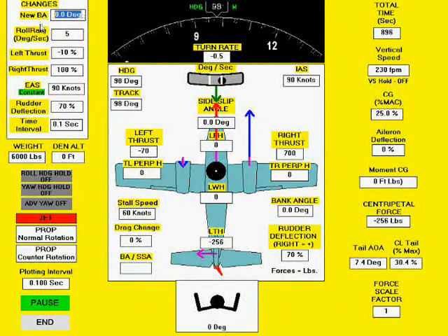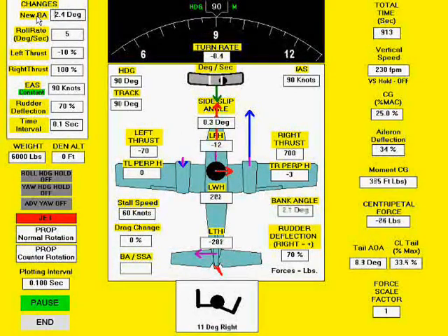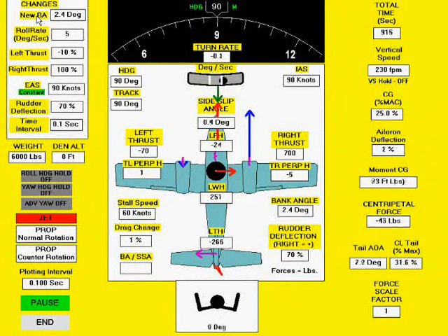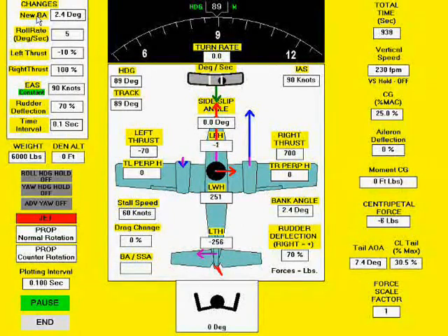Now, since we are turning in this 0 sideslip condition, we must establish slightly more than a 2-degree bank angle into the operating engine. We are now flying with a 0 sideslip angle and a constant heading while holding right rudder pressure, therefore applying the dead foot dead engine rule. A dead left foot means a dead left engine.